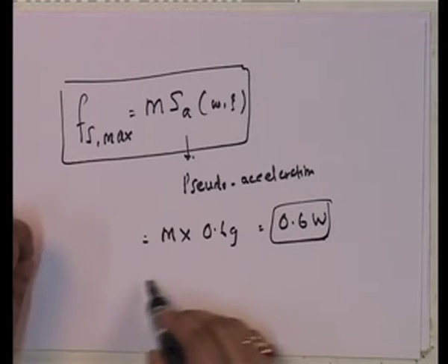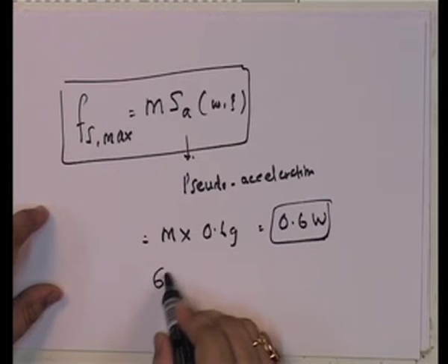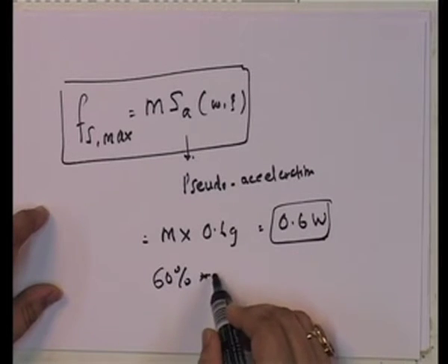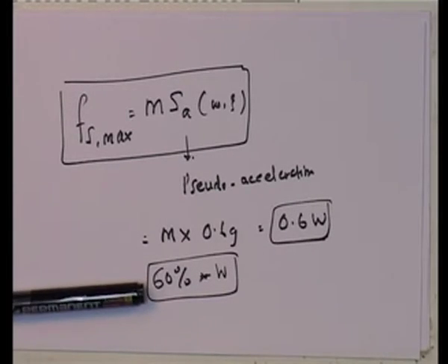So that means I know that the lateral force due to the El Centro ground motion is equal to 60% of the weight of the structure. I immediately know this. I did not have to do any computation or any structural dynamics. So, in other words, for a particular ground motion, if we have the pseudo acceleration response spectrum, we can directly get the forces that the structure is subjected to.